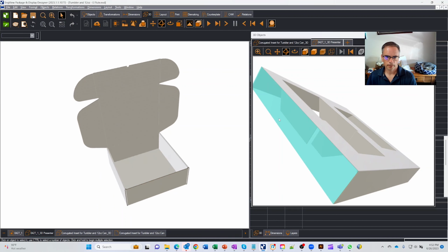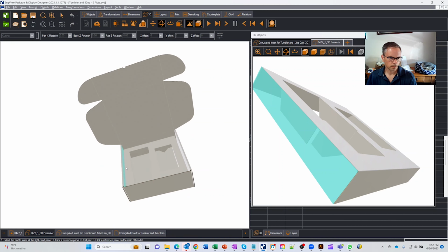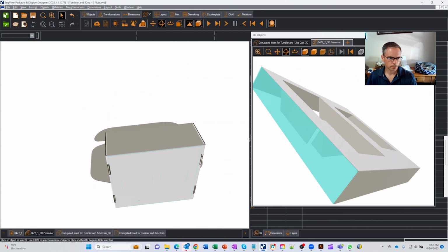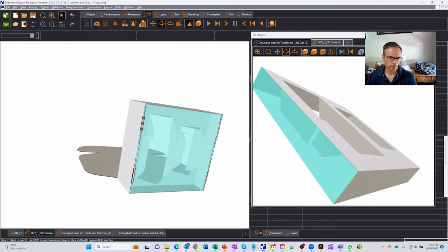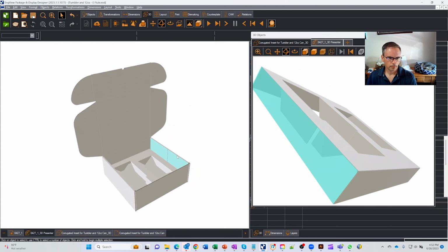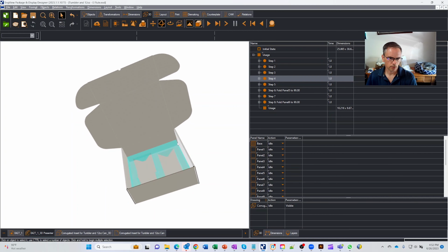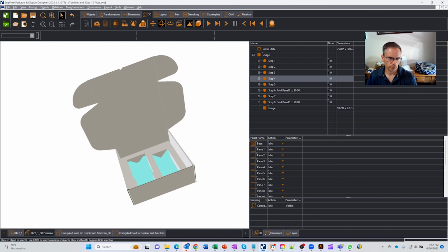So let's grab the edge of here and rotate our box around, and we are going to put it in the box. You can see it's actually protruding through the bottom just a hair. We can fix that because we can go grab the material thickness, and we can also make adjustments in the 3D, whatever we want. You can also see there's a slight gap on this side. There's none on this side. So when these tabs come down, we're going to want to move this over.